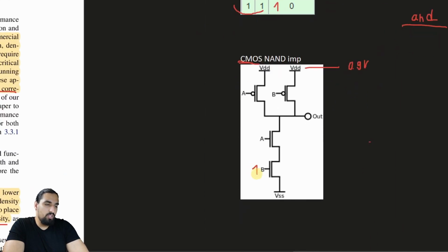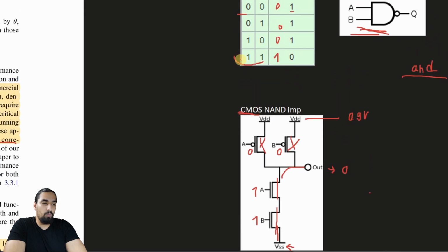So that's how you implement 0, and that's how you implement 1. And so if I feed 1s here, for example, that's 0.9 volts, and if you feed 1 here as well, and as you can see, this small circle again means it's inverted. So we'll be adding 0 onto this gate and 0 onto this gate. And what happens is, because you brought a huge voltage here, you're going to toggle on this transistor, and so the current will start to flow here and here, and you're going to block these two because you brought 0 voltage here. And so as you can see, you're basically making a direct connection to the output to this thing here. And let's say this is ground, so it's 0 volts, and basically that means your output is 0 volts, which is 0. So 1 1, you get 0.